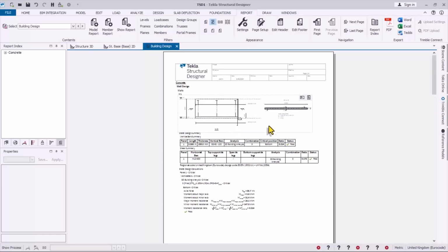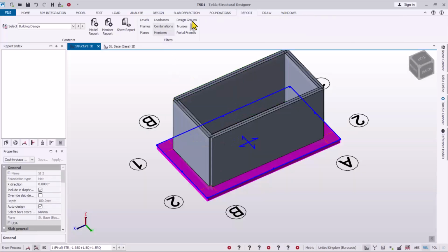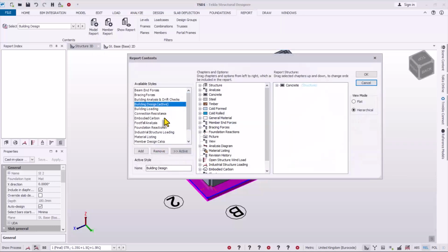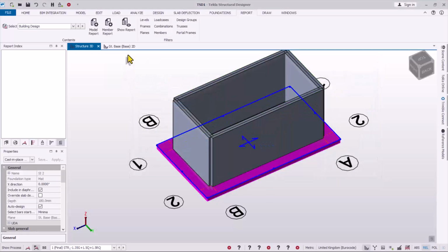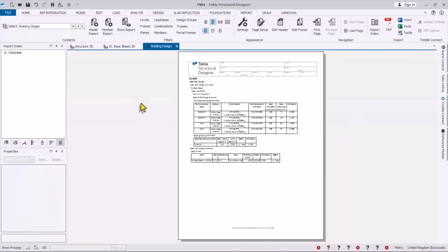Okay, let us produce the report for the mat slab. So I'll close this and then get to the report tab, and then over here for the model I'll click on these provisions. So this is design active. Okay, so over here what do we have? Only one. I'll expand this this time around. We need a report for slab mat design. Pull this to these provisions. That is just what we need. Click on the OK option, and then if you click here, this will be produced successfully.